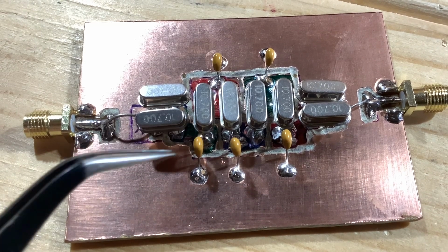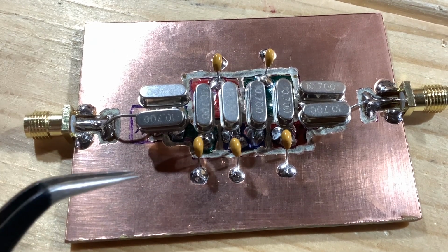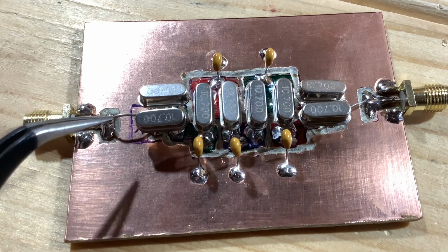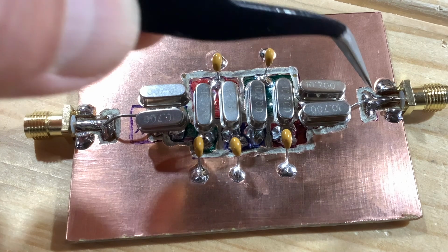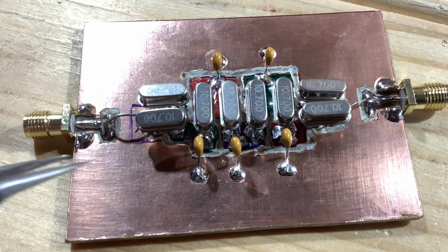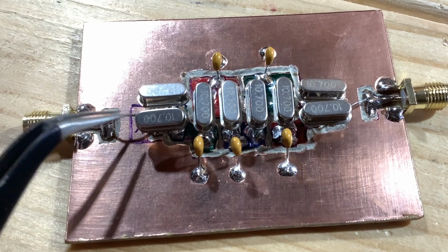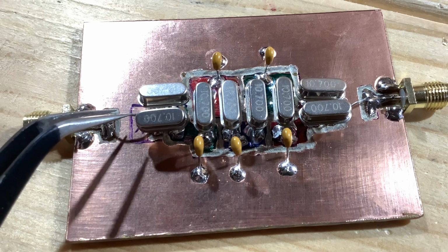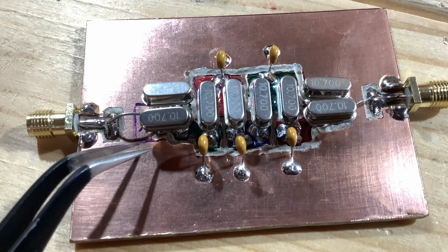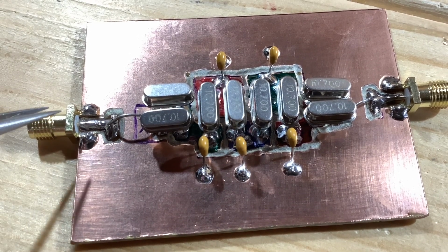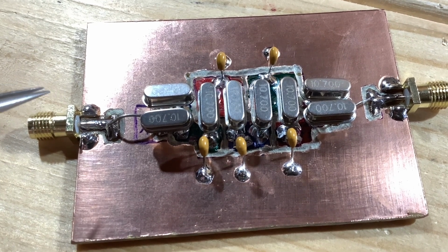And some of the first ones I built here, it was just too hard to get in and do it. So I've allowed plenty of room for that. You'll notice these little connections here and up here. This is where I will be having some impedance matching device, either a transformer or an L match network, something that will match to the impedance of the actual filter itself, to 50 ohms. But I haven't decided on what I'm going to do with that yet. But I've left space again.